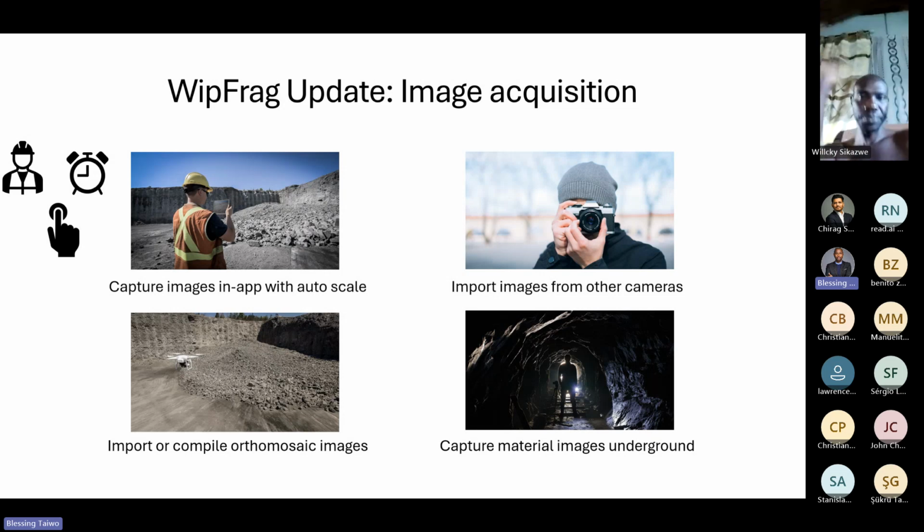So most of the boulders sometimes will be coming from the stemming region, forming the cap of the muck pile. With the drone image, you can take a bird's-eye view image of this material and analyze it to assess your material coming from the stemming region.